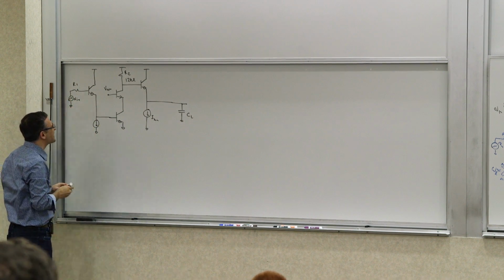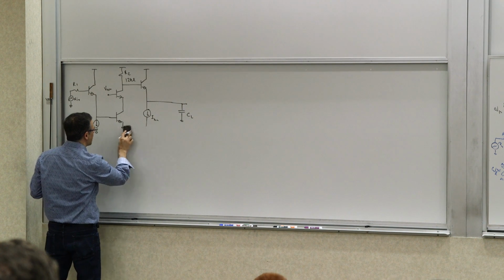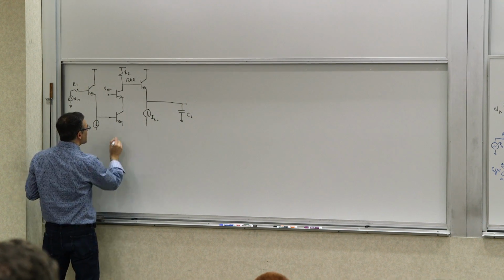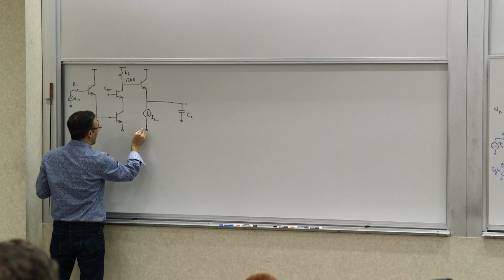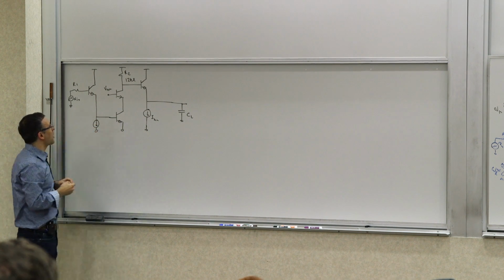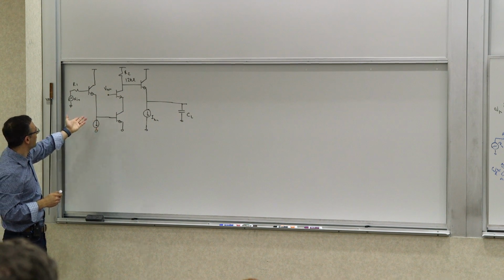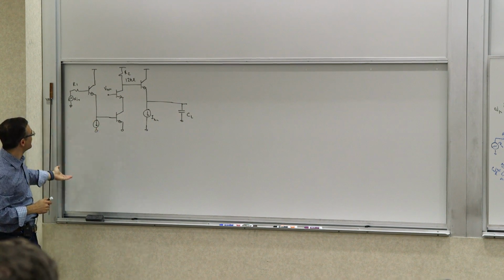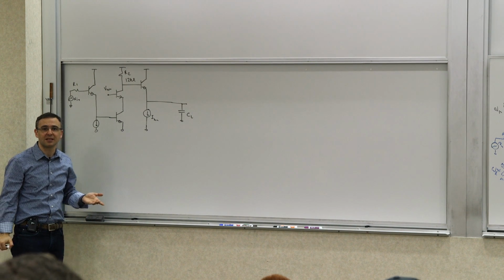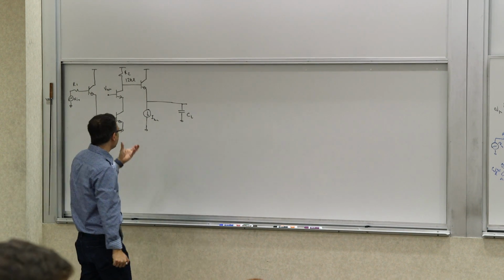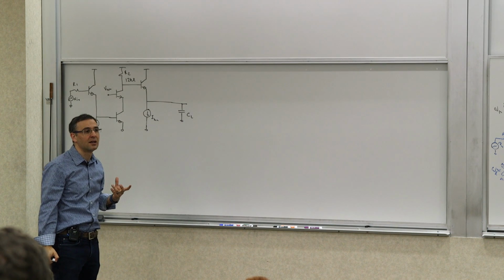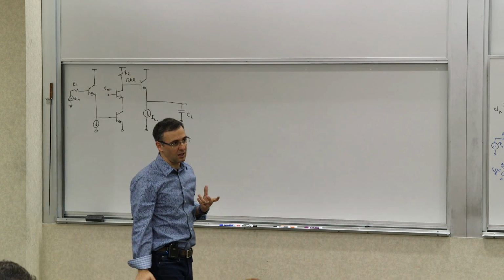So this is still a concept. Yes, it has the right ingredients, but this is not a complete design, right? You can't go to the stockroom and buy an ideal current source. And if you just connect it this way, you have to think about the DC levels, making sure the transistors remain in saturation, all those things. So now we can take this conceptual design and turn it into a real design.